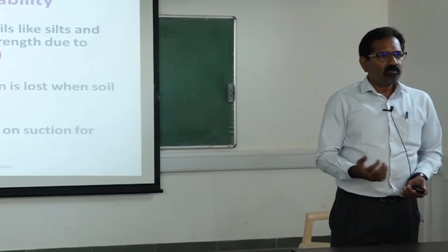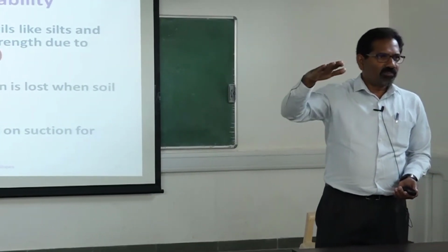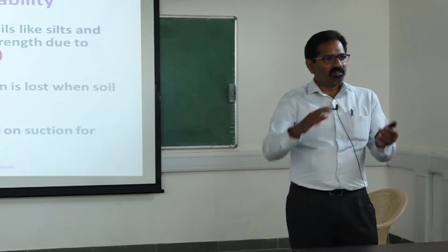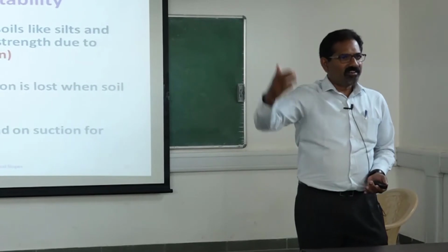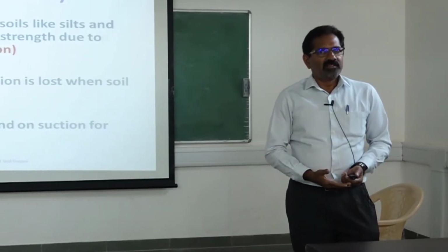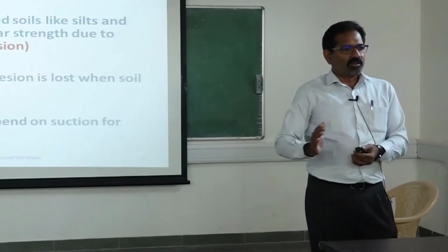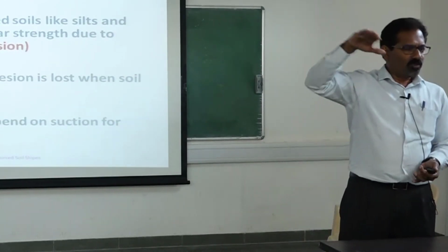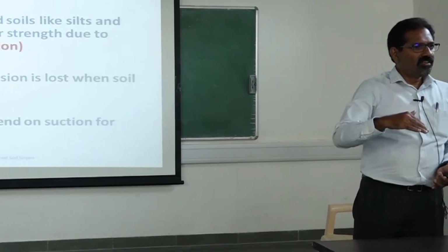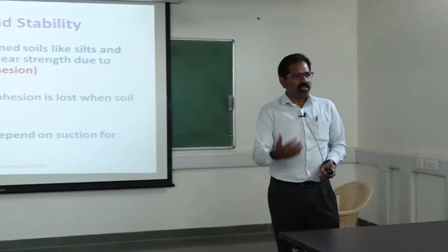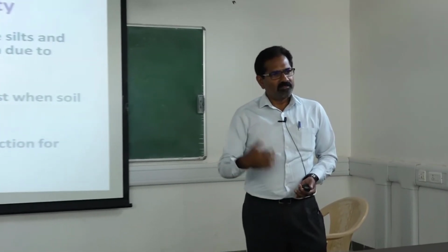But if that embankment is exposed and it rains over a period of many years, the soil becomes saturated. Then one sudden day, you find it has collapsed. So basically we have to consider short term and long term. In the short term, even a steep slope, 45 degrees, 60 degrees, even 90 degrees, may remain stable, but not for very long. Over a period of time, it will collapse.